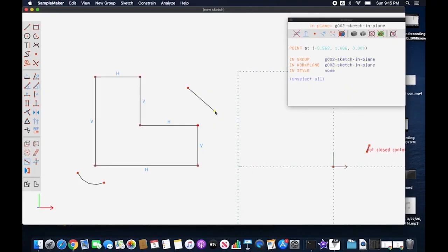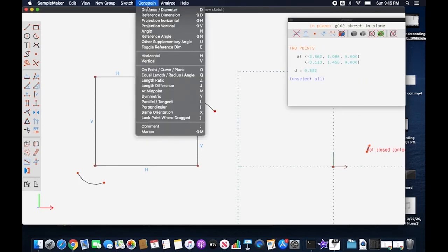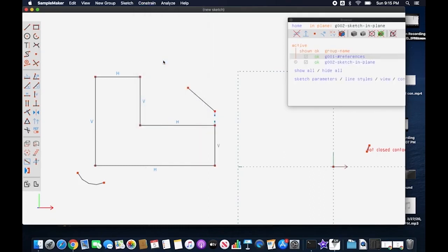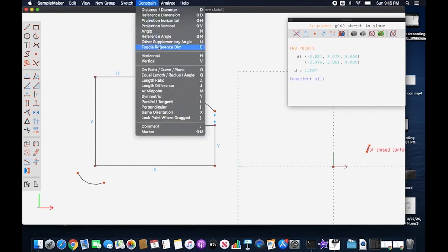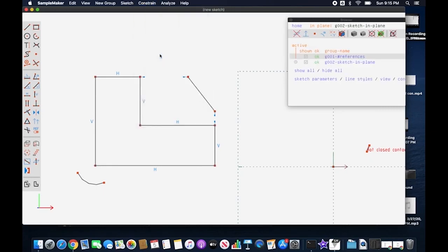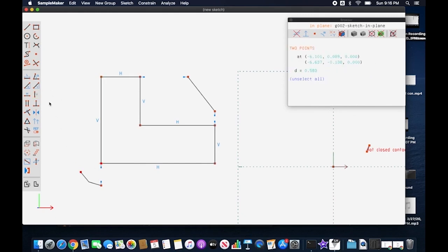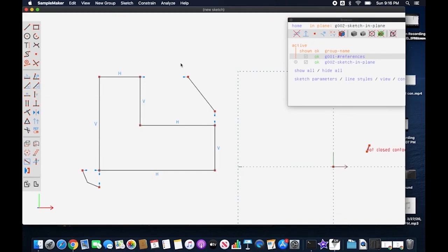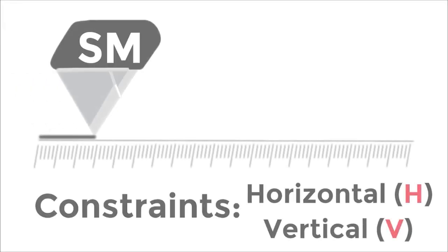In this section, I'm going to do some vertical projections, and you'll notice when I come in and do them, which is going to be Shift V, it matters where I click first. So notice I'll click here first, and then I'll click to this point, and then when I do my vertical projection, you'll notice that it went up to that point. So if I pick that spot first, then this one, and do a vertical projection, it'll project to there. If I do here, I'm going to swap back to a horizontal. So I picked that point first, and it moved it up to that spot.